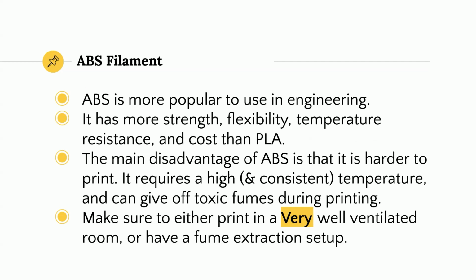It requires a high and very consistent temperature, so your printer nozzle needs to go at a higher temperature, and the temperature needs to be consistent, so you cannot have major changes in temperature, otherwise the print is not going to work. And also, more importantly, it can give off toxic fumes. You don't want to breathe that in.